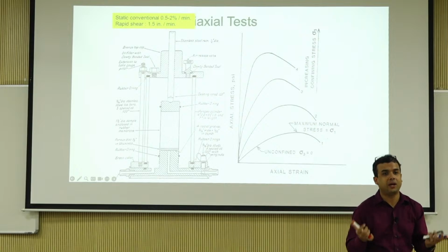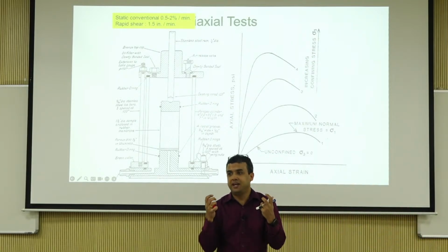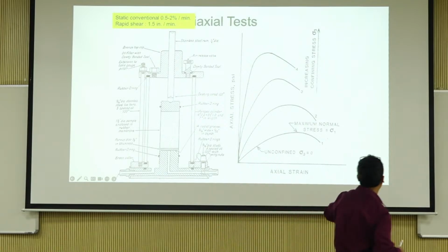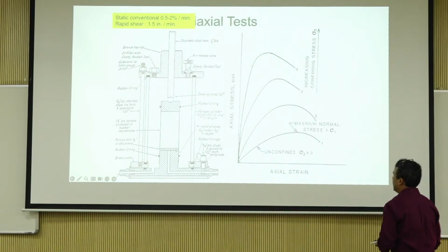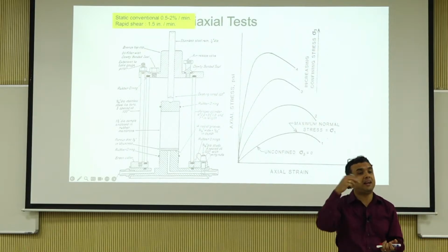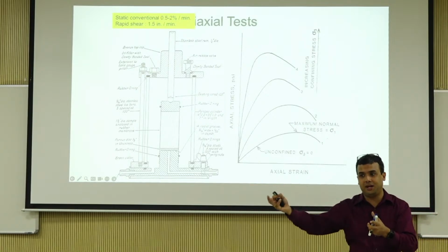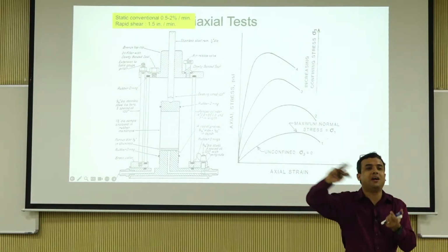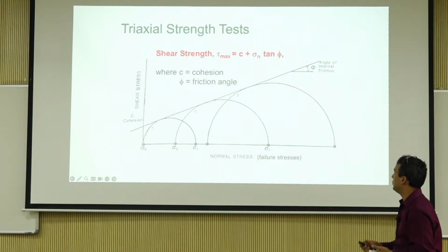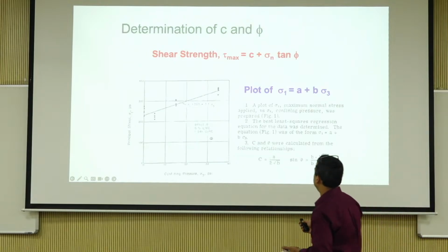Once it is held together, because the particles don't crush, you actually have an immense amount of strength, right? So that is the reason confining will increase your shear strength a lot of times, as long as it is being translated into interparticle contact. If it is saturated, if it is undrained condition, if water is taking all the load, soil does not care, right? That's what happens. You saw this. We're going to do this in the tutorial today.